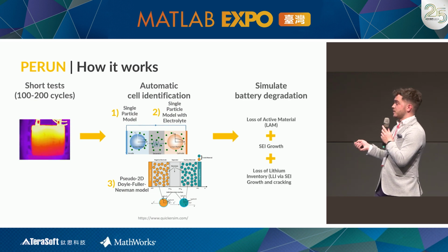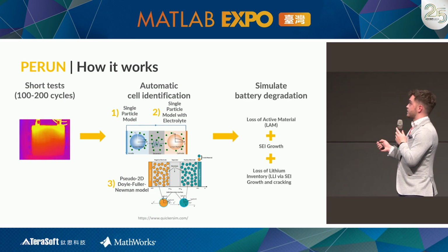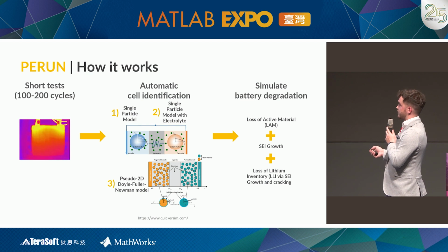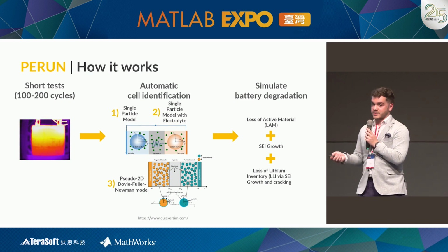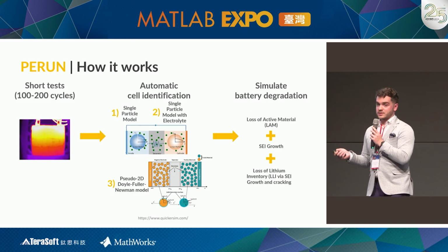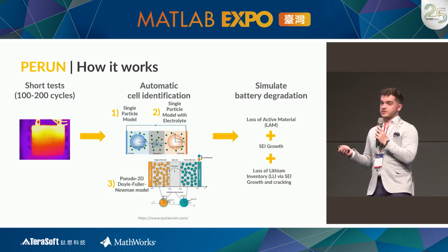And then using those models and combining them with 3 degradation models, so loss of active material, SEI growth, and loss of lithium inventory through growth and cracking, we can simulate how the battery cell will degrade.